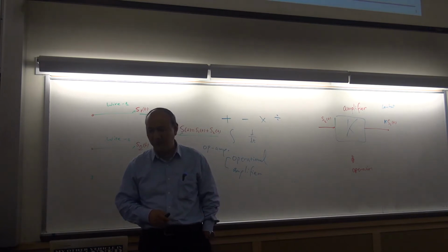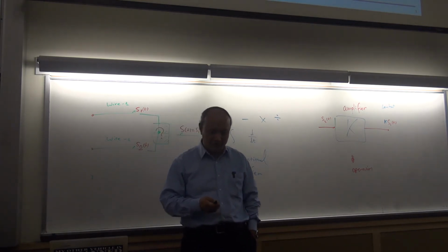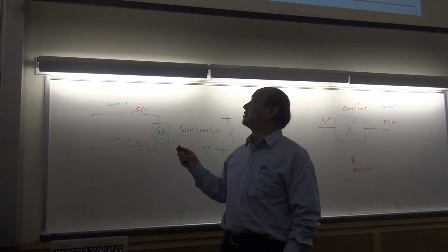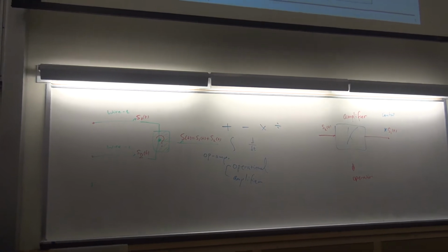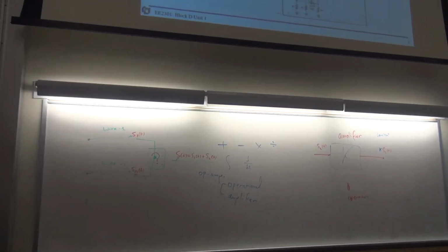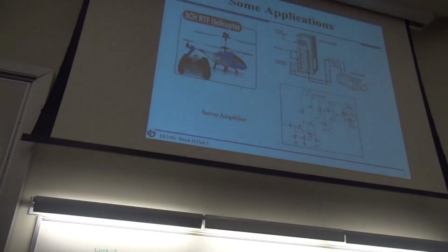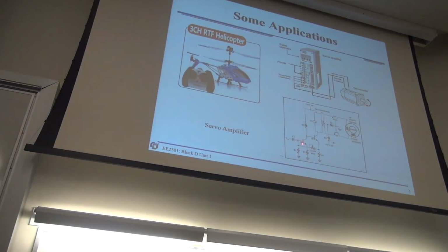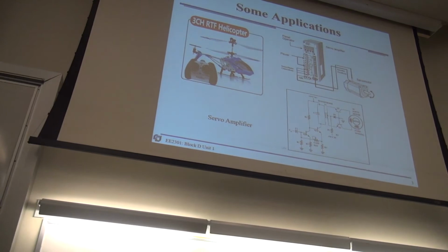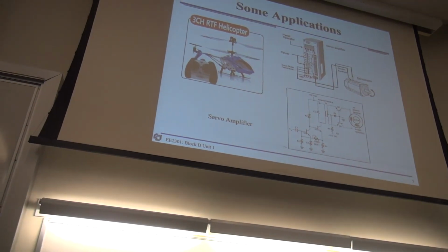There's also a servo amplifier. If you have a simple signal, the signal cannot drive the motor because the motor needs power to turn, right? However, your control signal is so weak, you cannot do that. You have to amplify it. It turns out that this is the final amplification, okay?